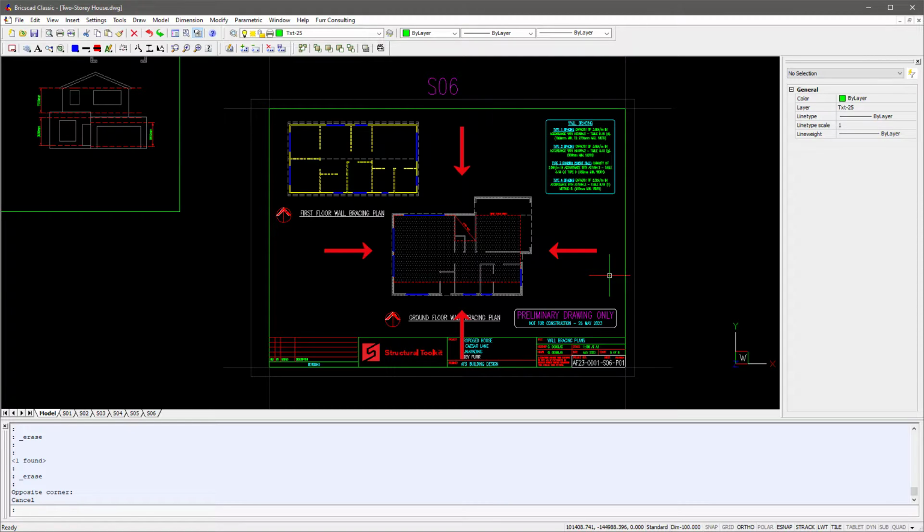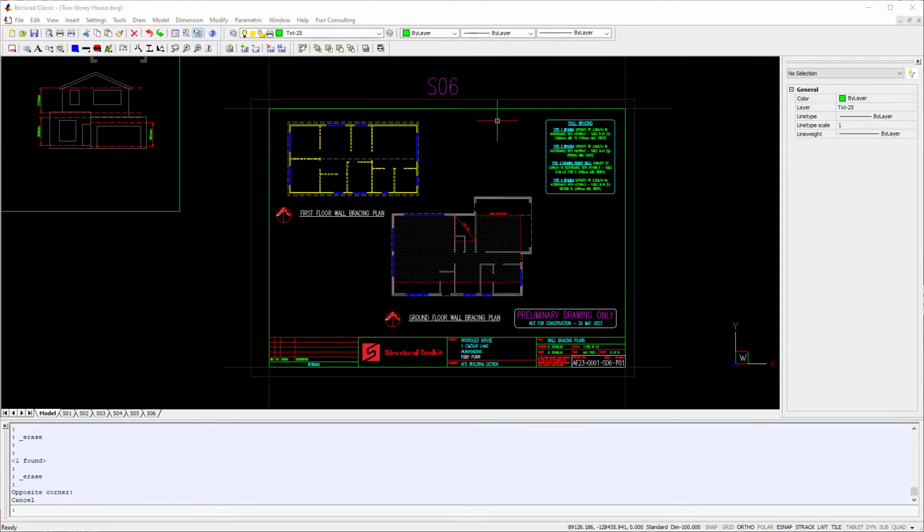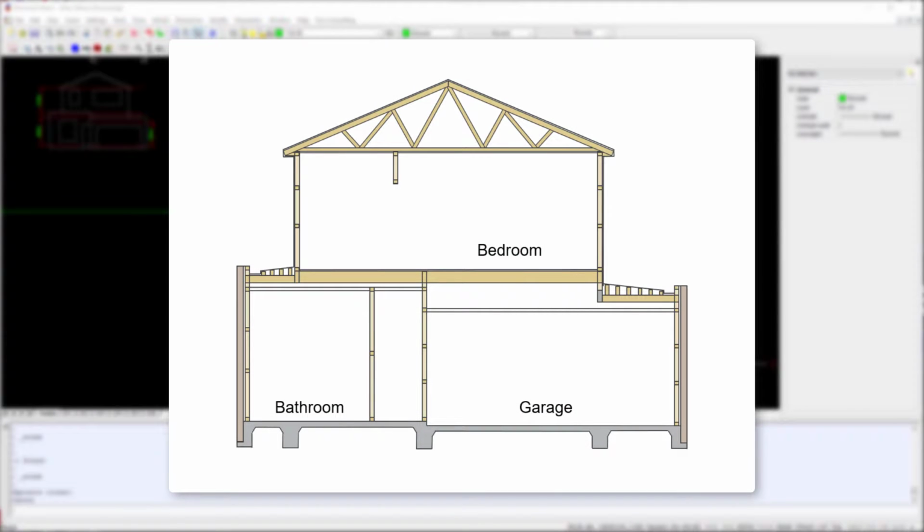What we want to achieve here is to design a system that will transfer the wind loads over the building all the way to the ground. In simple terms, the way this will work is our forces in the upper roof transfer via bracing straps provided by the truss manufacturer or engineer for where rafters are used to external and internal upper braced walls.